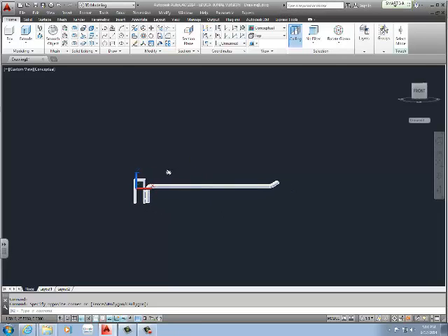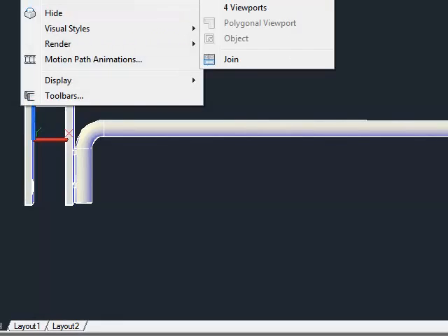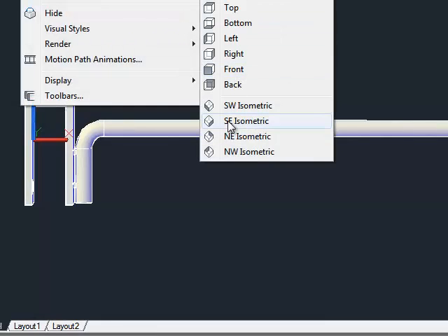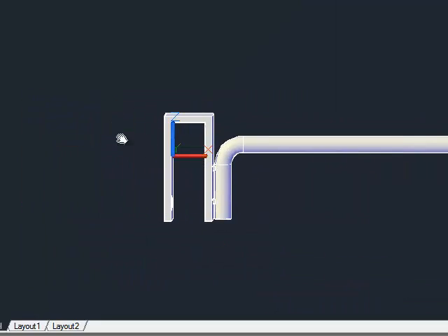So what else I want to show you about this project is, if you do want to create the 2D drawings of this, it's pretty much a half-inch tube with a bracket, without actually starting over from scratch. What you can do is a flatshot. Basically, you start out by looking flat at the object. Flatshot creates 2D drawings based on the reference view you are currently in and your UCS setup.